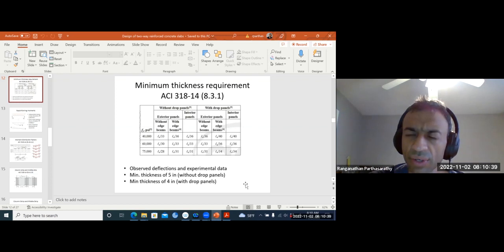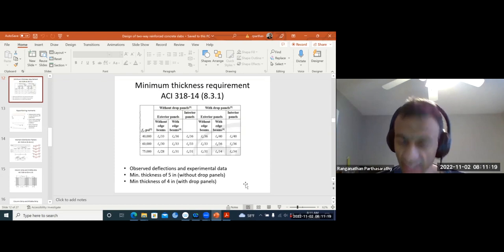your reinforcement and your slab thickness will ultimately be adjusted for your load. This is your first starting point in the design, to assume the thickness. And as you go through the design, if your loads are especially high, if it is some non-standard kind of loading like heavy machinery and so on, then we need to do the detailed serviceability calculations as we saw in the beginning when we were doing serviceability. Yeah, we do need to explicitly calculate deflections.